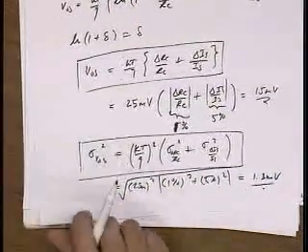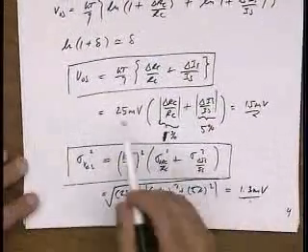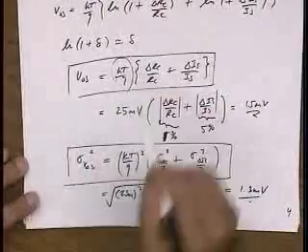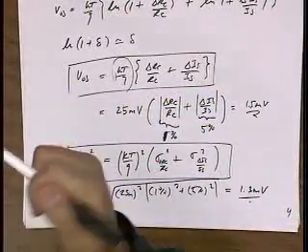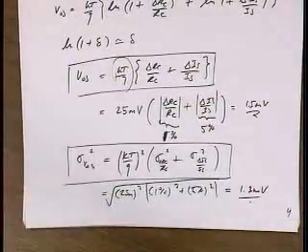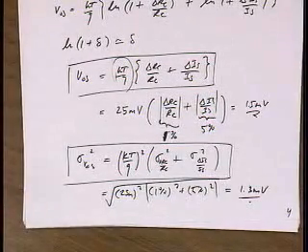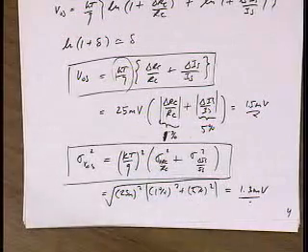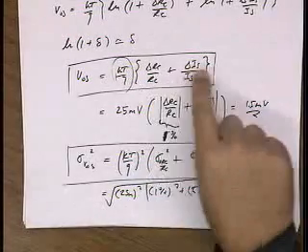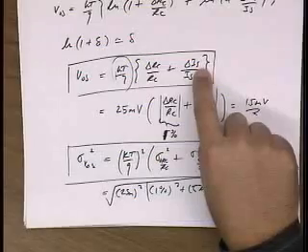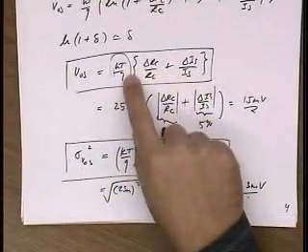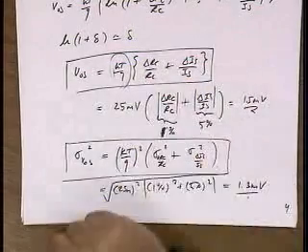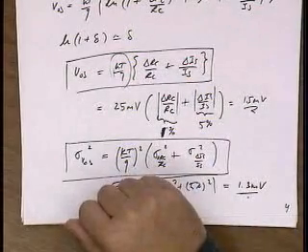The other important thing to observe here is that there's a temperature coefficient. If I go out and null this offset, just like we talked about before with, let's say, another resistor, then that will null at one temperature, but it will not track over temperature. That's because the delta IS has temperature dependence, delta RC has temperature dependence, and there's a temperature dependence here. So clearly this will vary with temperature.